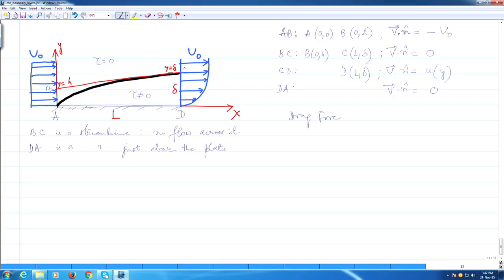So, my drag force will be, right, this is a unit vector in the direction of positive x. And of course, pressure acts uniformly on all the surfaces, so forces due to pressure are 0, uniform pressure. So, therefore, let us try to sum this up. Now, therefore, sigma Fx, which is equal to D. When I say Fx, I am talking about the total forces in the x direction, and that, like we said, is this.